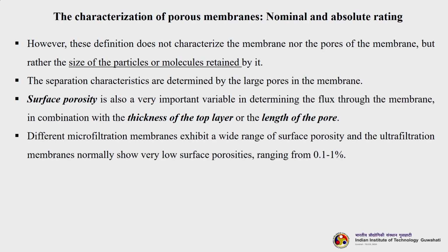However, this definition does not characterize the membrane or the pores of the membrane, but rather the size of the particles or molecules that are retained by it, since the separation characteristics are determined by the larger pores in the membrane. Another important feature is surface porosity. Surface porosity is also a very important variable in determining the flux through the membrane, in combination with the thickness of the top layer as well as the length of the pores.